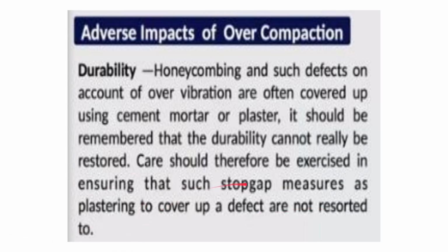So just covering a defect can be a short term solution, but the appearance of the defect is suggestive of the fact that the quality of the concrete is not good, okay, because the honeycombing has occurred. So it has occurred because of the over compaction. So instead of solving the problem, it's better not to create the problem in the first place, okay. That is why it's called prevention is always better than cure, okay.